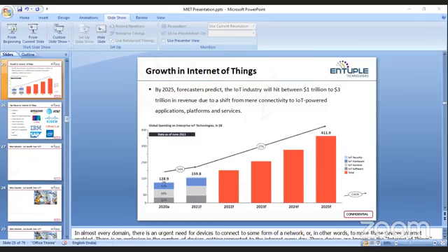In IoT, we use different connectivity technologies depending on the project. If the project is within your home, we can go with Wi-Fi. If it is, let's consider, a smart building within a campus, then we can go with LoRa or Zigbee. So the connectivity technology we choose depends on the project.